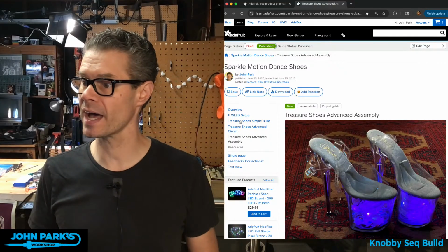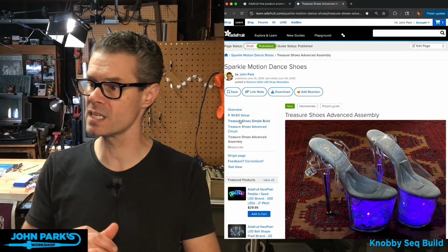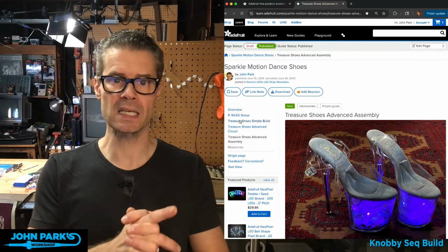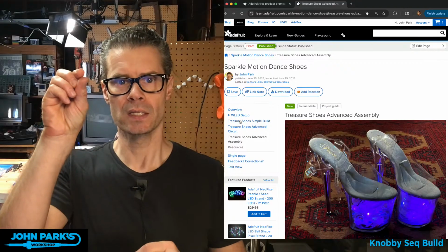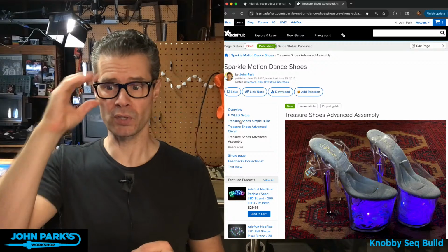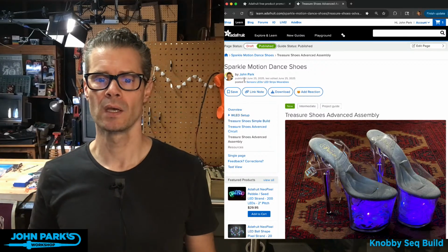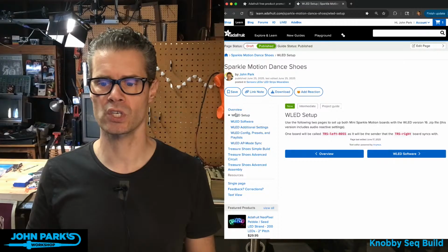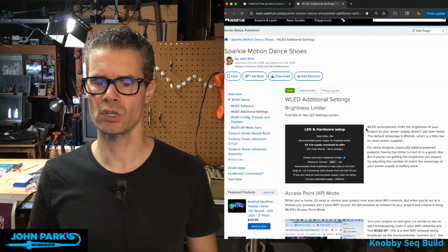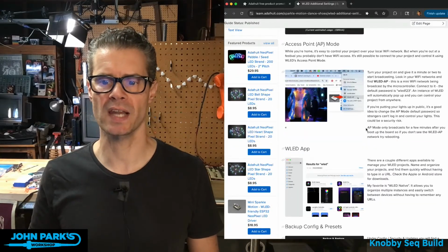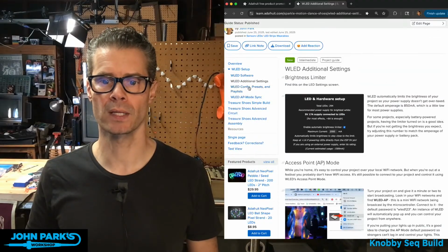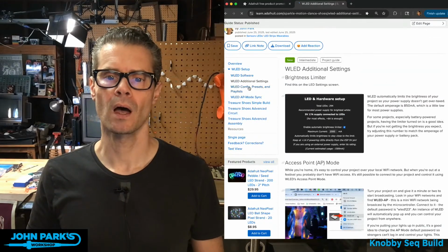Couple questions from the chat about, Mouse said, how do you do FFT? It is built into the WLED software, and we have a digital PDM microphone built onto the Sparkle Motion. So in the WLED settings, which I can show here, under, I believe, additional settings, I've got setting this up as an access point. Actually, this is a mirror from one of Aaron's guides on WLED.